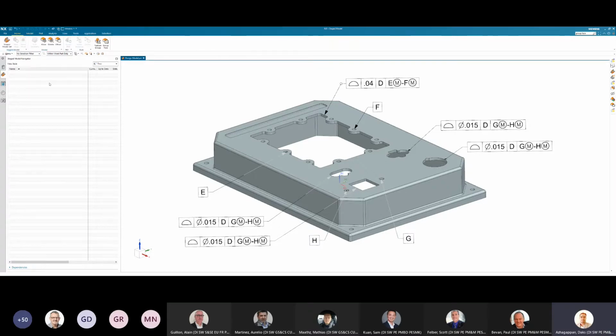So in this case, I'm going to start with the starting part of the process, which is to create stage. When I click on the stage model set, that's the first function to start with. It basically takes the product data that I have on my screen. You can define the number of stages to start with. You can start with 1, or you can also start with 6 or 7. If you have bill of process information, looking at that, I need probably 15 operations. I can simply create the 15 operations and start with that.